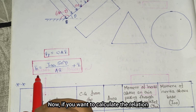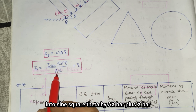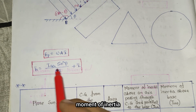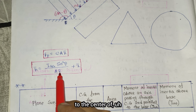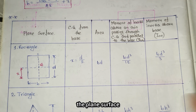Now if you want to calculate the relation between h bar and x bar, h bar is equal to Igg into sine square theta by A x bar, plus x bar. So Igg is the moment of inertia about the center of gravity, theta is the angle, A is the area of the plate, and x bar is the distance from the free surface to the center of gravity. Okay, and plus x bar. So remember this formula.